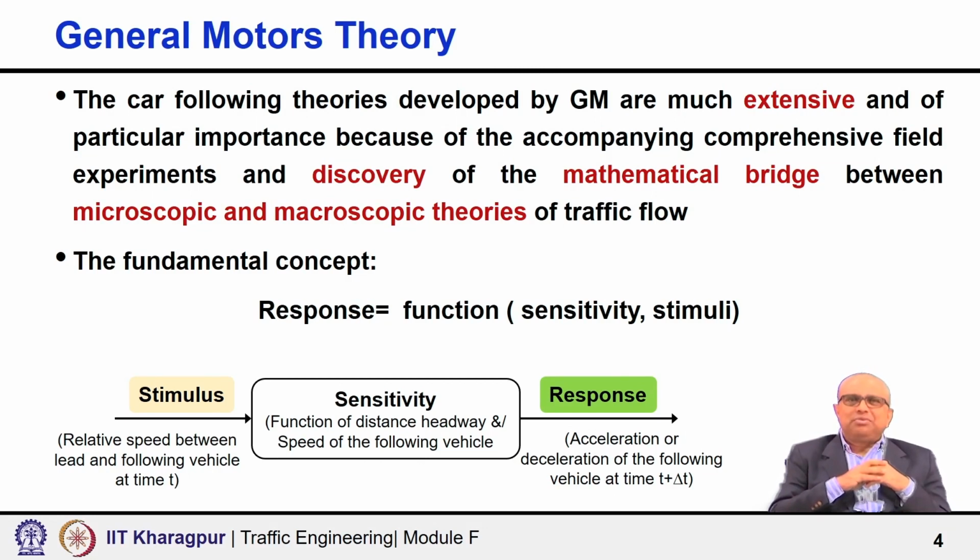Sensitivity is a function of, as you will see, distance headway and speed of the following vehicle. And the response is the acceleration or deceleration of the following vehicle at time t plus delta t. So, whatever the stimulus at t and the sensitivity, accordingly the response at time t plus delta t, in terms of acceleration and deceleration, is modeled as part of the car following model.